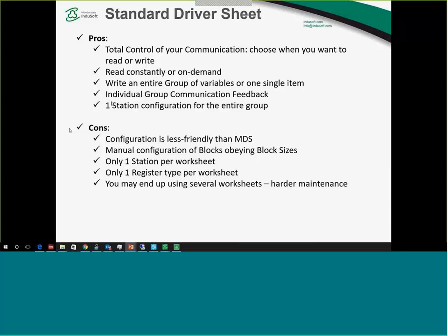And you only configure the station field once for the entire group. The cons. The configuration is less friendly than standard driver sheet because you have full control, you have more things to configure. There is a manual configuration obeying the block sizes. On Modbus, you can usually go up to 125 words per block. So you have to keep that in mind when you're configuring each main driver sheet. You're going to have 125 words from the PLC, okay?